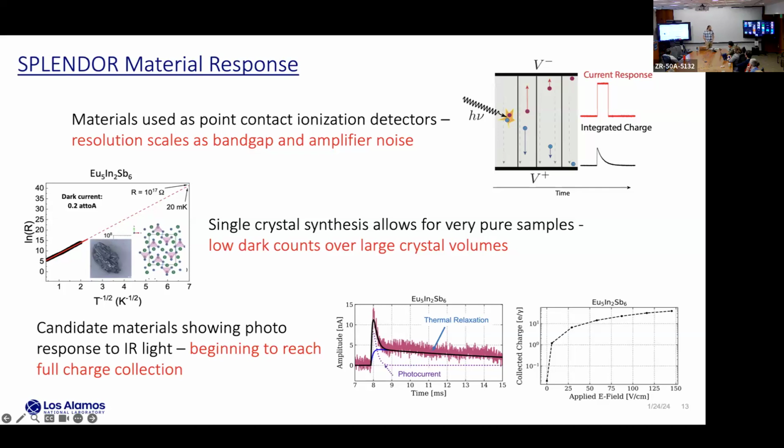Another thing that makes this project unique over using another kind of artificial low band gap material, for example mercury cadmium telluride, which is what they make night vision goggles out of: those are heavily doped systems that create an artificial band gap based on an overabundance of impurity states. The problem is they have a lot of dark count rates because you have all these impurities in there.